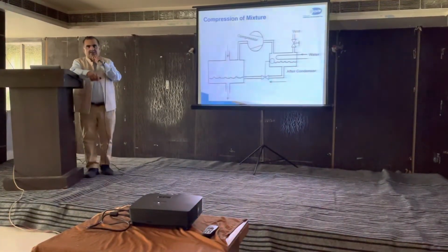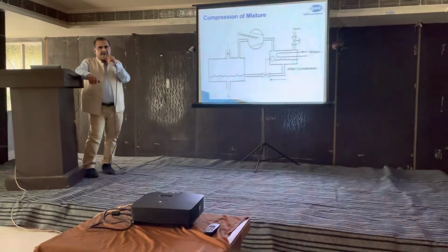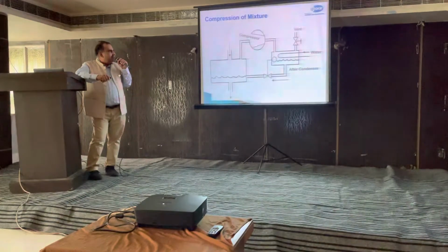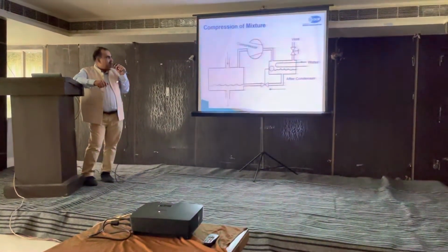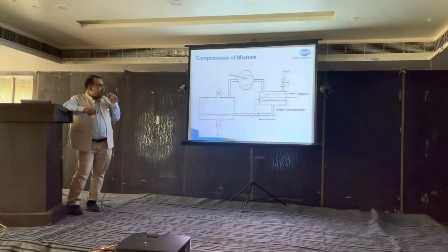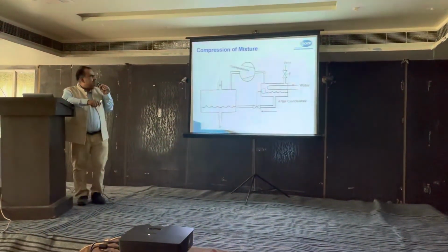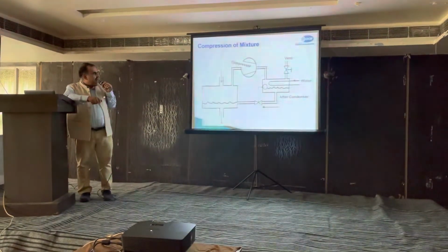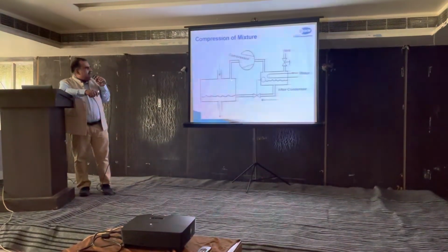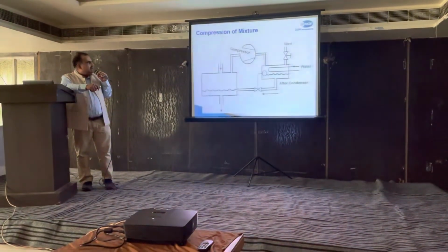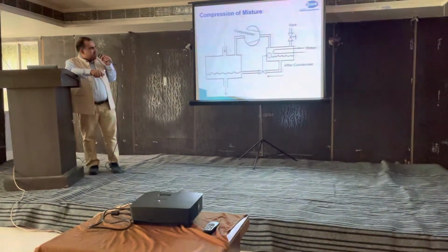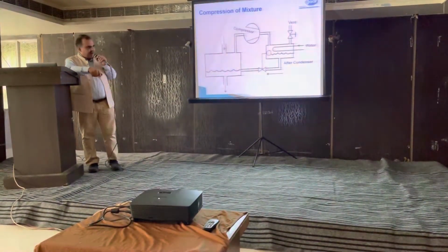So another option for this alternative is to go for an automatic purging system. In automatic purging systems, there are two types of purgers. One is using an external condensing unit with a compressor, and then there is another evaporator which this system uses to cool. It is installed above the receiver or condenser, and the foul gas is taken into the compressor. It is condensed, and if there is ammonia, it is pulled back to the system. And if it is not condensable, it is vented out.